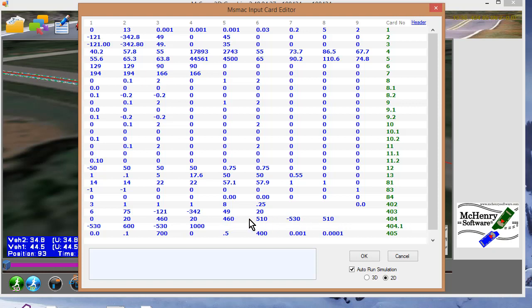Now, you may see that these are the same distance. That's because there also is the ability to spiral. You could spiral between 510 and 600 from the positive to negative, etc., depending on the path of the roadway or if your actual roadway design has a spiral transition. That's why you don't have to have these the same, but if you do have them the same, then what it does, it'll run 460 up to that point and then change to minus 530 after that point, and then we just leave it at minus 530.